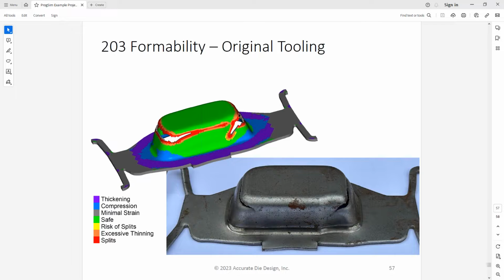But a lot of times when a part starts to fail, very little simulation software out there probably does show you exactly where the failure is. They'll certainly show where the thinning is. They'll all be the same with that, or the ones that are right will show you where the thinning starts, but exactly what the crack looks like, this one might always be a flyer, because again, once cracking starts, it's hard to determine where it goes, and it's really not so important to see where it goes. It's important to know when it starts.